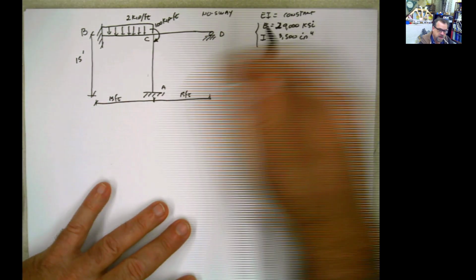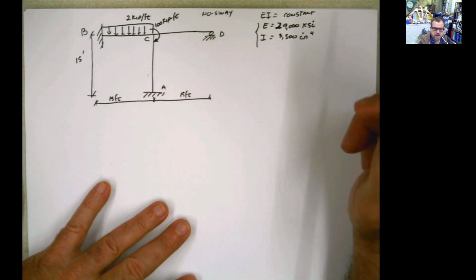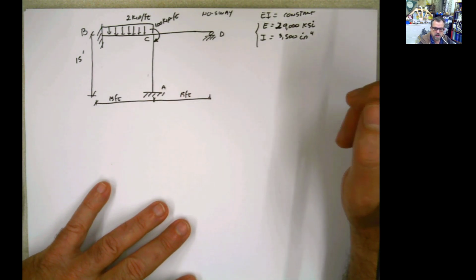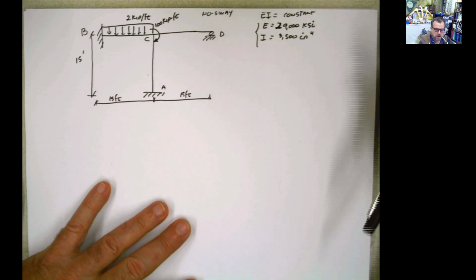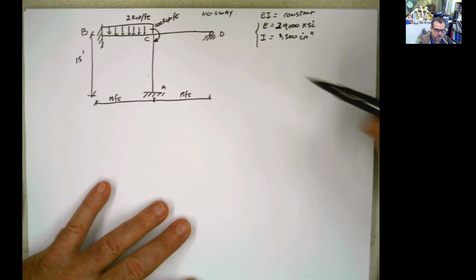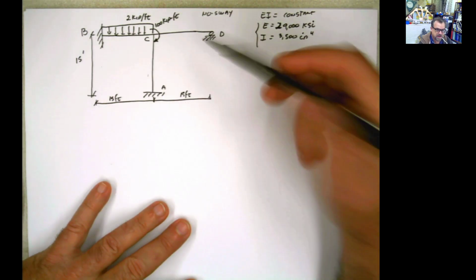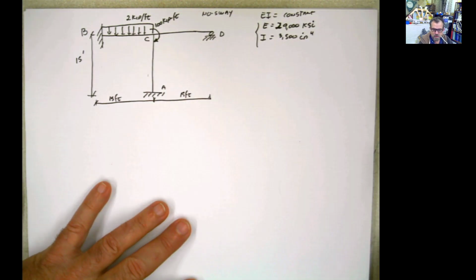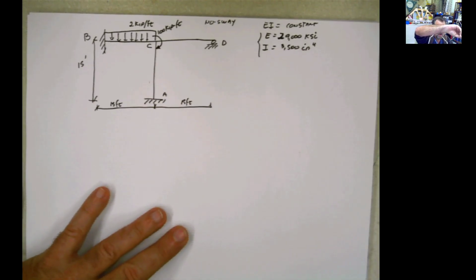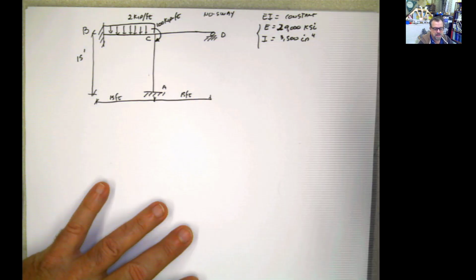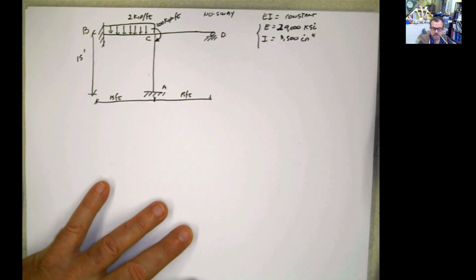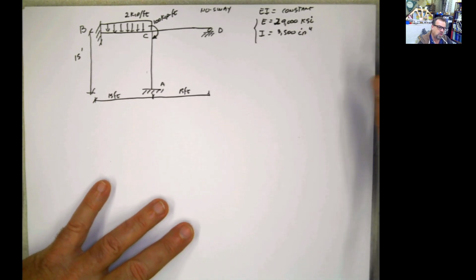First step. We did this, by the way. There is a video of this using slope deflection, and it was a fairly good amount of work. But imagine this once again. I always ask the same thing: can you imagine this solved by the method of forces? That is the method of consistent deformations, which is the real name of the method. You have 7 unknowns here, which means that you have to select 4 redundants and work with 4 different combinations of deformations.